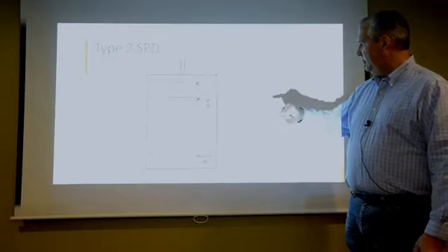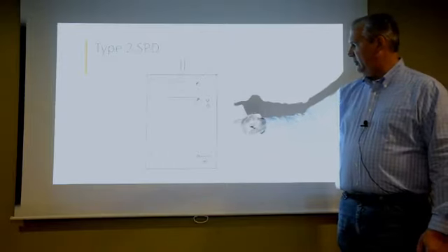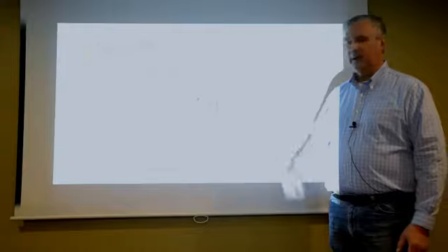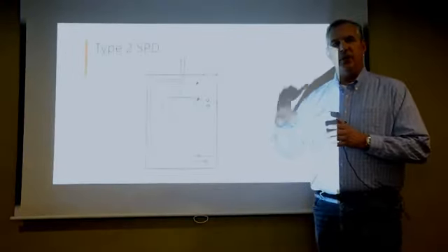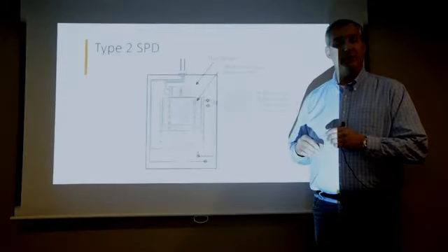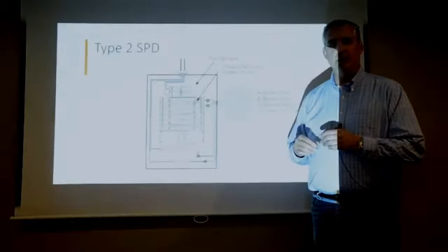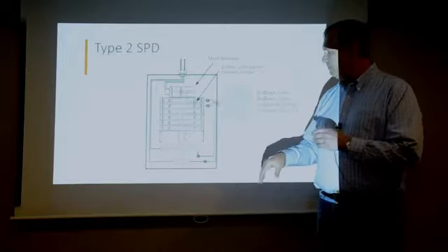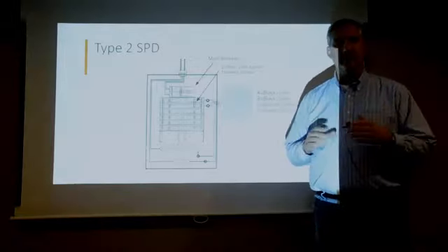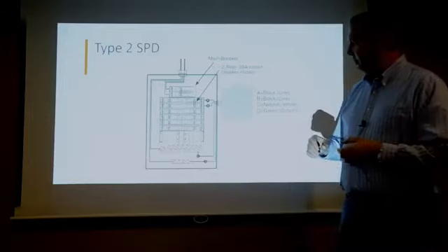You have two lines, a neutral and a ground connection with that surge protector, and it sits there and takes thousands of hits and shaves off any of the surges that we talked about earlier to a safe level and dumps them to ground. And that's why the ground connection and proper grounding are very important.